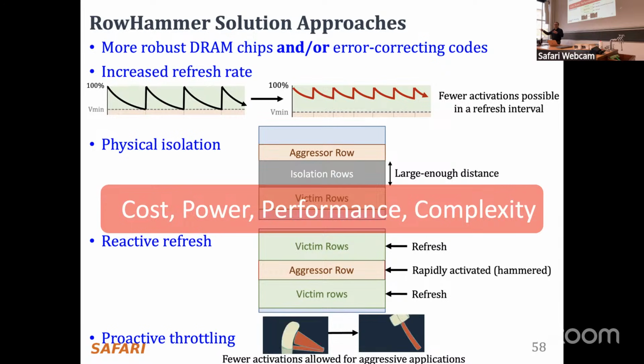But moving the row somewhere else takes a lot of data movement, right? So it's good to think about that. Fundamentally, it's a different approach. It can also be agnostic of the DRAM chip's internals. That's the advantage. But moving the row somewhere else is something that we want to reduce as much as possible, based on the lectures on processing in memory. We don't want to incur more data movement. We want to incur less data movement as much as possible. But there are works in that direction. Some of them add internal DRAM support so that you can do this row data movement relatively quickly inside the subarray, building on ideas like RowClone, for example. So there's another approach over here that's not on the slides.